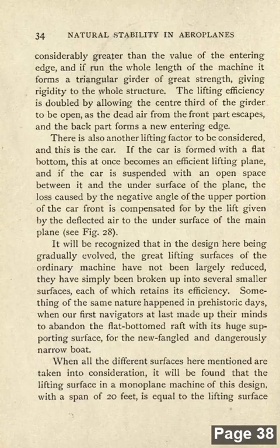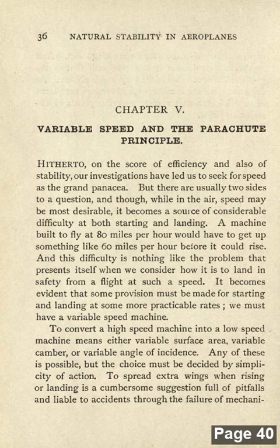When all the different surfaces here mentioned are taken into consideration, it will be found that the lifting surface in a monoplane machine of this design, with a span of 20 feet, is equal to the lifting surface of an ordinary biplane with a span of 40 feet. And as the head resistance is less than half that of a biplane, speed should be very much greater. At the same time, the increased speed renders the planes more efficient, area for area, than the planes of the slower machine.